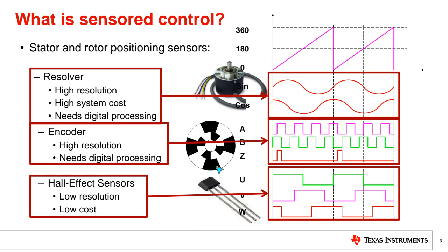And the last one, the Hall sensor. You see here it has low resolution with respect to the encoder. To compare these three sensors, lastly I said resolvers give you high resolution and very accurate position. Encoders have higher resolution than Hall effect sensors, but lower resolution than resolvers. Hall sensors give you low resolution, but they are simpler and lower cost to implement.